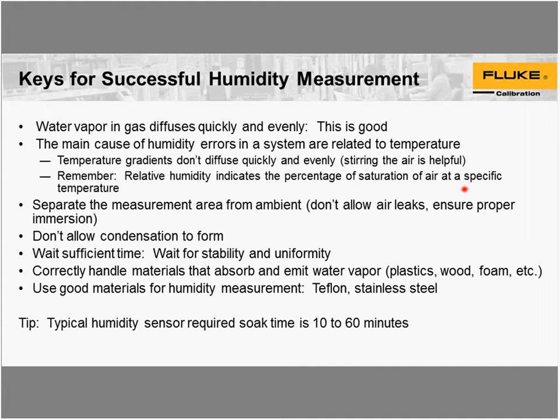We already talked about this. When you are measuring humidity, it's critical that the measurement area is isolated from ambient. So working with a chamber, make sure you don't have air leaks, and also make sure that you have proper immersion. Those of you who work in temperature know the importance of sufficient immersion for temperature sensors. Well, it's the same principle here. The humidity chamber is basically an air bath. You have to make sure that you don't let temperature gradients from outside influence what's going on on the inside.